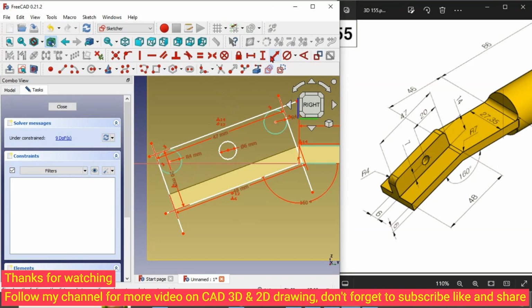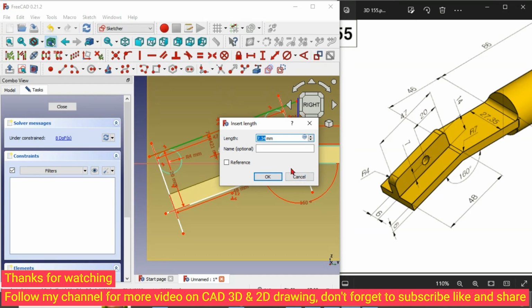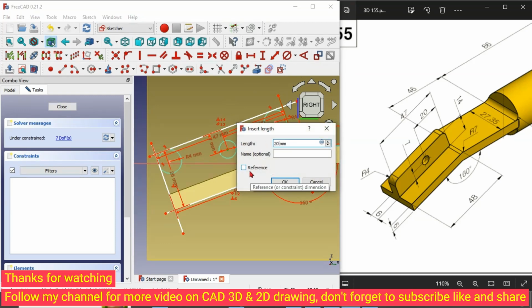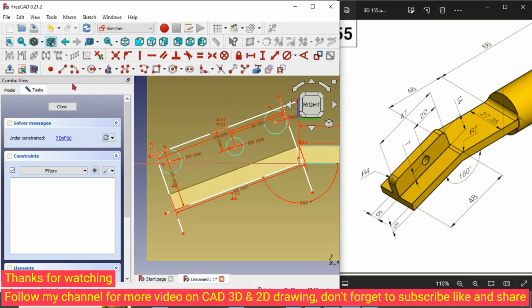Then we set the distance from this center of the circle to this line to be 7. Why 7? Because this whole block is 14 in height, so from the bottom to here is 7, and up here also 7. Then from the end here to the center of the circle is 20. So we set the distance, the circle to this end of the block is 20. Okay, done. And we can proceed to trim.